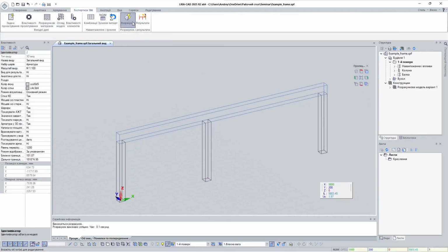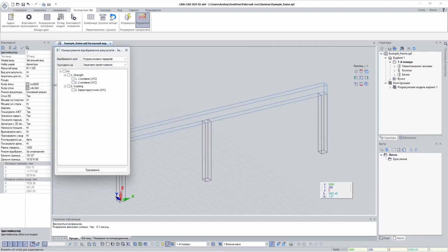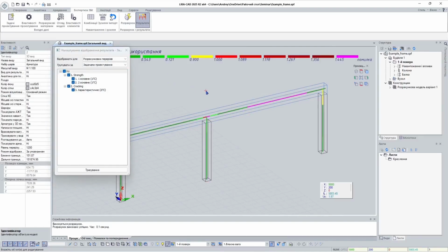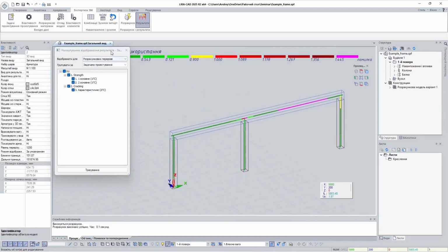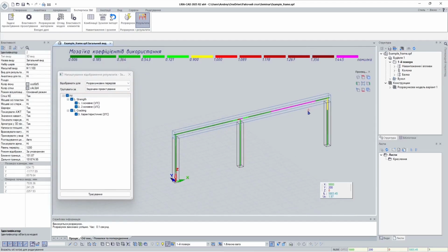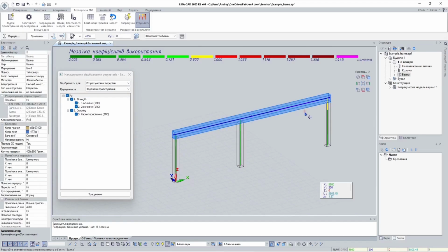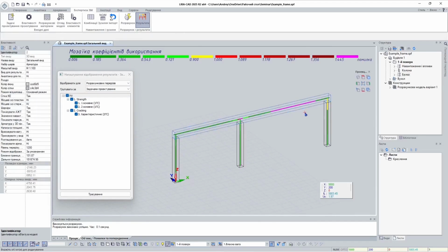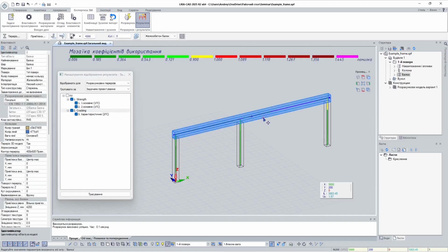Wow, okay. So you can literally trace every single number in the result right back to the input data. It gives you complete transparency into how the system arrived at that utilization factor. That sounds incredibly valuable for verification and just understanding the design. Absolutely. You could use it to check, say, the normal section strength of your columns, or maybe check a slab using DBN requirements, that's just an example code, and see exactly how forces determined by, say, the Wood-Armer method were used in the check. Full traceability. That level of detail is fantastic.